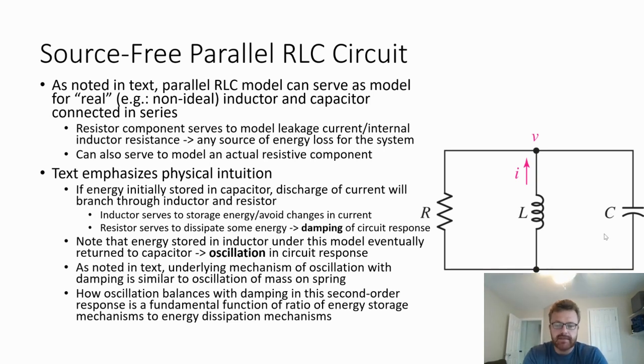Now, one of the things your text emphasizes that's just worth noting very quickly is in practice, this could be used to model a circuit that only contained an inductor and capacitor, and you might say, well, where would the resistor come in? Well, remember, in practice, a capacitor is not purely insulative. It's not purely an open circuit. That dielectric will have a little bit of leakage to it. That leakage current will result in actual energy loss, and this resistor could be used to just model the loss of energy due to that leakage current.